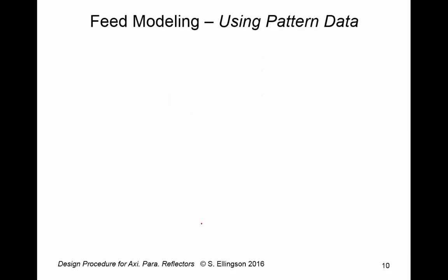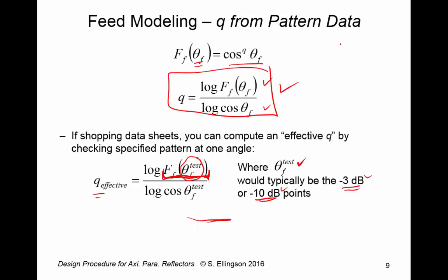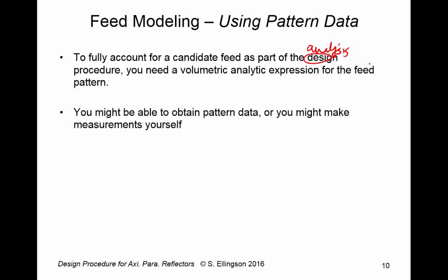Okay, now using pattern data. To account for a candidate feed as part of the design procedure, you need a volumetric analytic expression for the feed pattern. Now we're talking about the analysis phase here, right? In the previous slide, we were talking about the synthesis phase. This is talking about analysis, feed modeling. Now, you might be able to obtain pattern data. Perhaps the vendor provides it, or perhaps your organization can make these measurements.